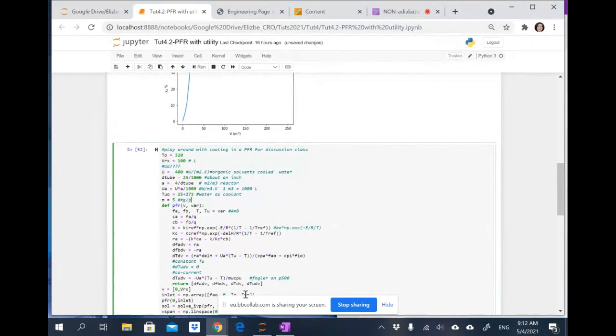This is in kilograms per second, 5 kilograms per second. This is a lot. Because when I want to get a feeling for how much it is, I always calculate how many tons do I have to transport per hour. So this is going to give me about 18 tons in an hour. Am I correct? Because it's that times 3,600. So that's 18,000 tons per hour. It's not unrealistic. It's possible to do.